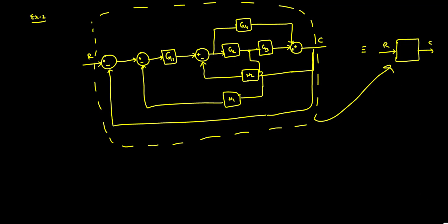One important thing that you already know is that if it is one feedback path, it is G by 1 plus GH. Those things are very clear to you. Now let us go one by one path to make it very simple. Suppose firstly I transfer this to here, here the effect of G2 is coming. If I transfer this here, the effect of G2 will not be there. So if I transfer from this point to here, the effect of G2 will not be there.